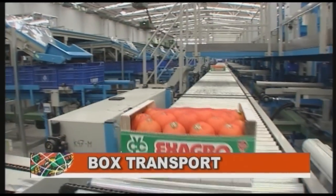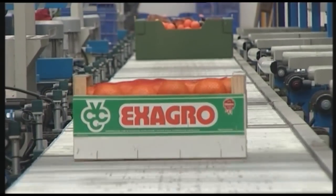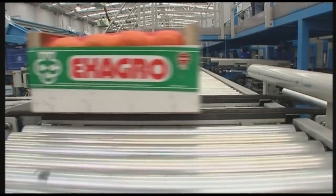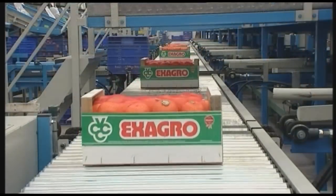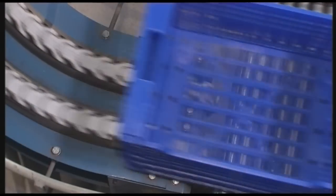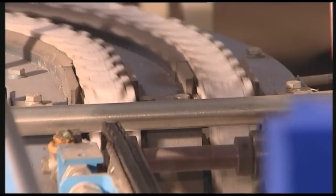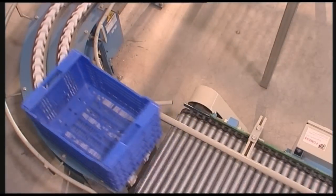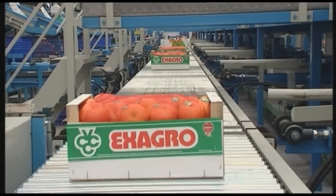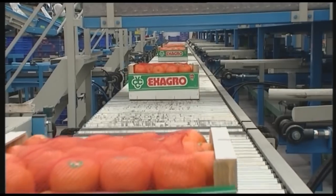The supply and transport of boxes is carried out by means of chain conveyors circulating on guides made of wear-resistant plastic. The chain is replaced by a hinge conveyor when a change of direction is required. This special hinge conveyor can be adapted to 90-degree or 45-degree curves or used in straight sections. In accordance with the requirements of each installation, motorized roller conveyors, collectors with transfer and belt conveyors, among other equipment, can also be manufactured.